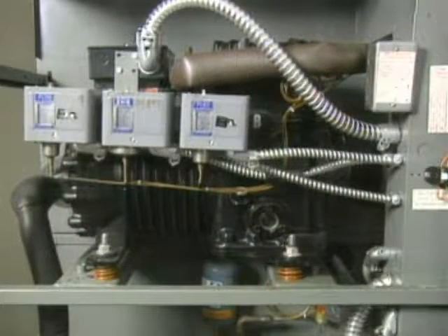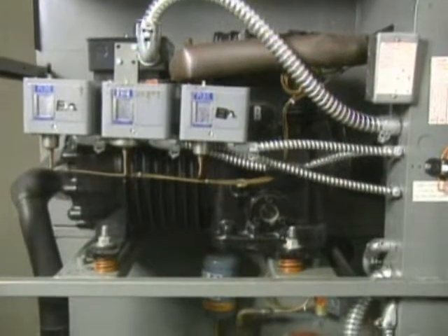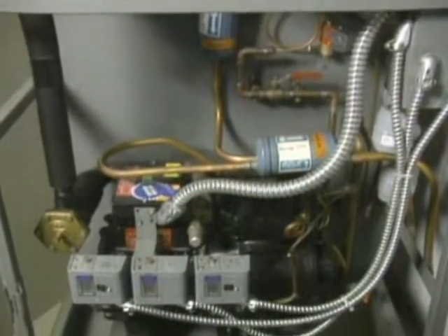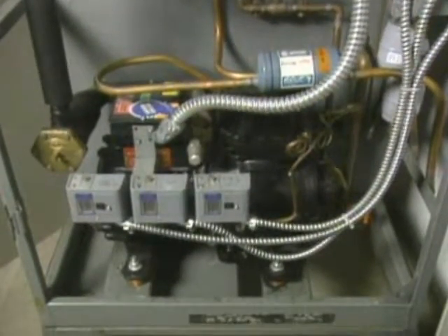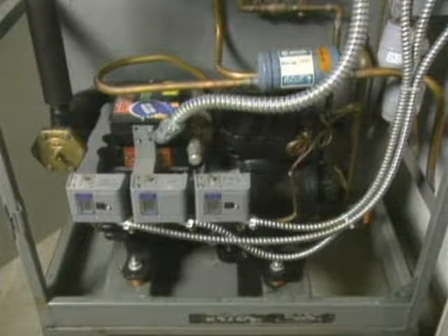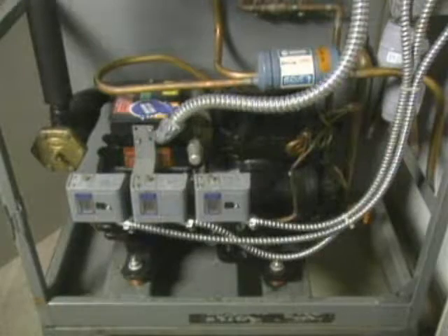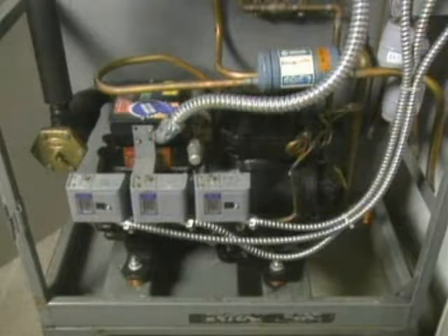Another indication of too little refrigerant may be a continuously operating compressor. Some types of refrigeration systems cycle the compressor on and off to maintain the proper cooling. If this type of system has too little refrigerant, the compressor may run continuously, trying to maintain the desired amount of cooling. A similar problem is low refrigerant flow.